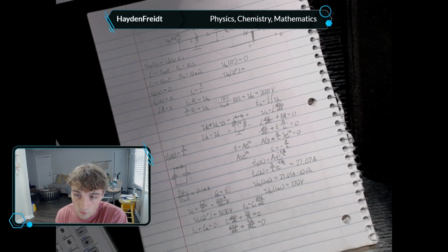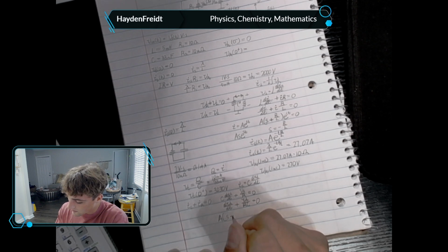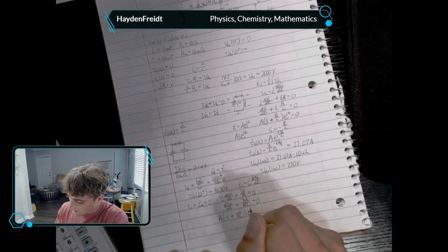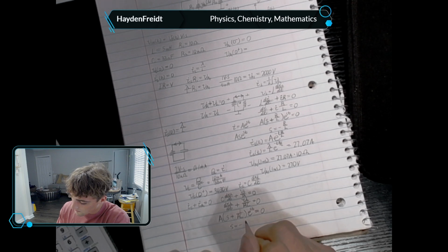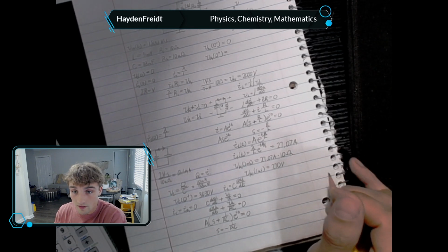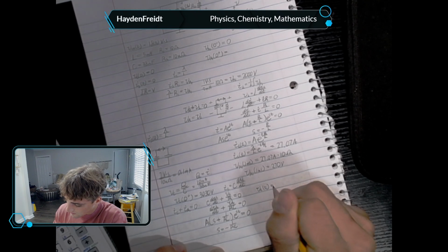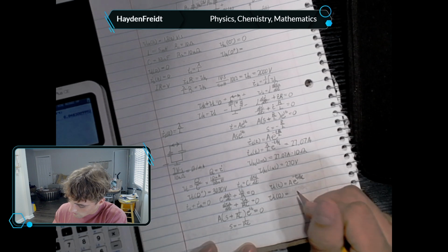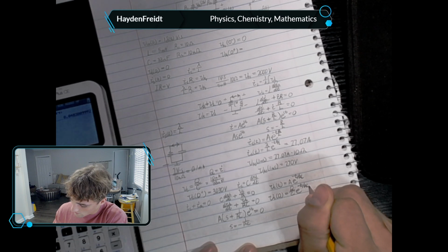Again, we're going to assume the solution. Pull the similar terms out, and we put our derivative as S, 1 over RC times e to the power of st equals 0. Therefore, S equals negative 1 over RC. We'll plug that in now, and then by initial conditions, we'll find our coefficient. VC of t equals 0 equals, let's say, Q over C times e to the negative t divided by RC. Plug that in.